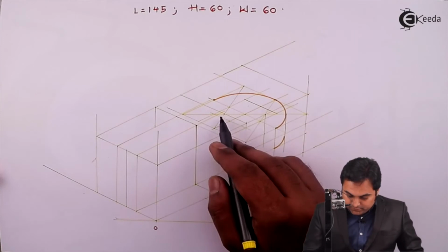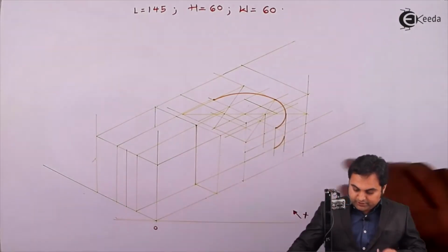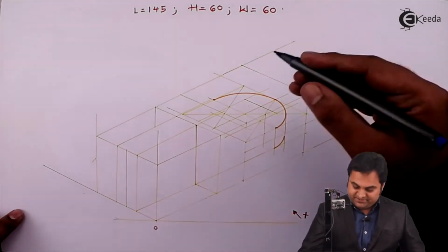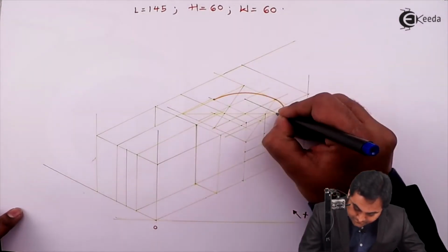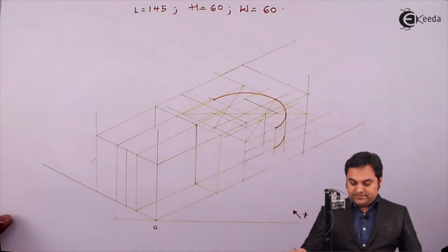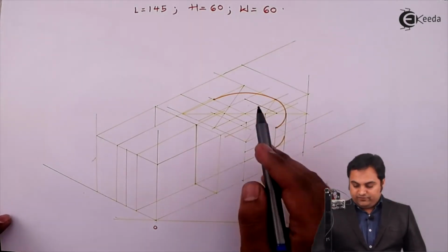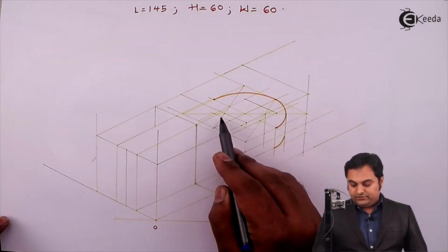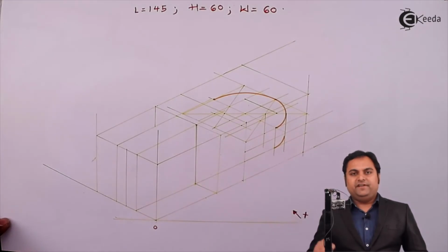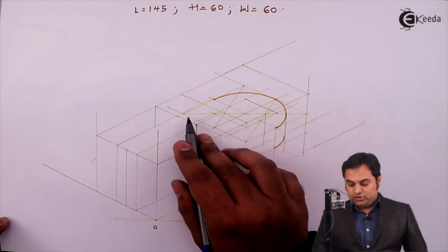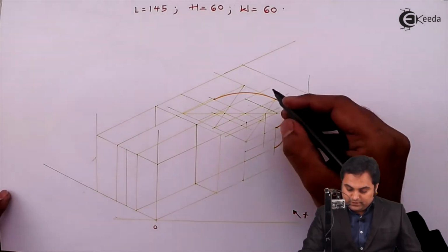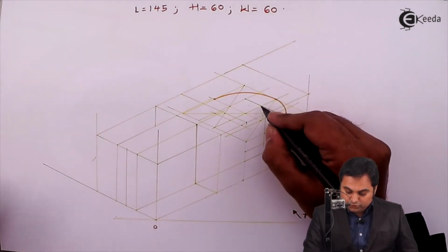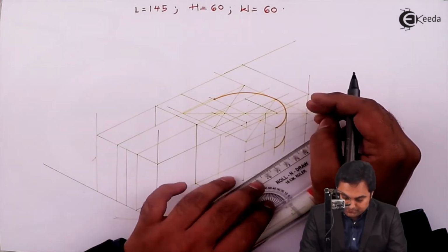Now, here I had drawn the parallelogram. I'll explain where it is. These are the corners of the parallelogram. After getting these corners, next the procedure is same. First to draw the longer diagonal, and here the longer diagonal is already existing because it is same for both the parallelograms. Then I'll join the top midpoint to the bottom corner.